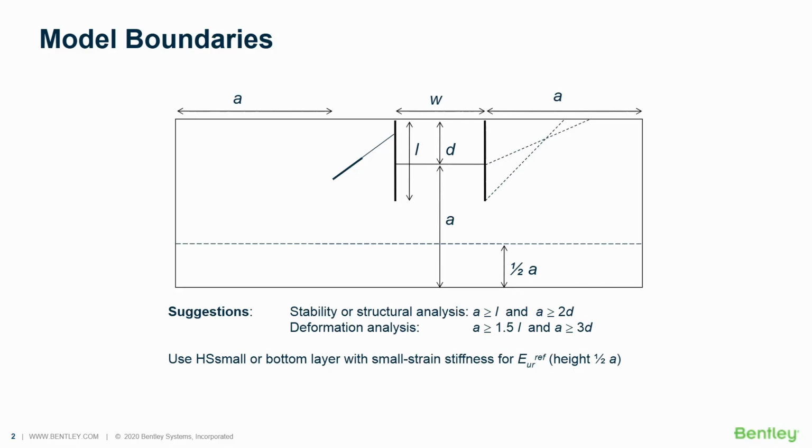And again, a model that you could judge to be too large will not really harm, because Plaxis automatically adapts the reference element size to the size of the model. So a larger model is not necessarily a model that will contain more elements. A larger model will consist of a model with slightly larger average element size, but with the same number of elements. And because in Plaxis, and especially in Plaxis 2D, we are using higher order elements, still the result will